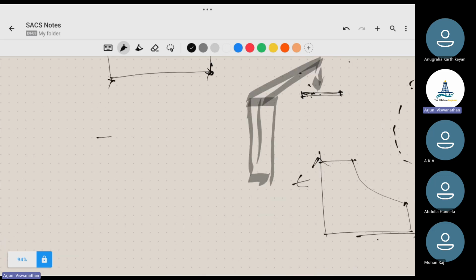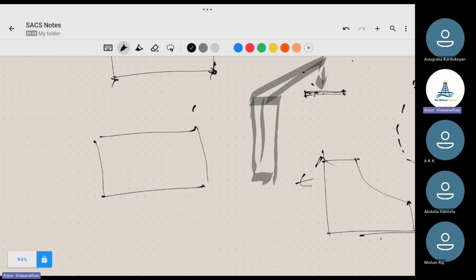Now, if I look at the plan view, there are two approaches to providing the weak springs. The weak springs we provide have 10 kilonewton per meter stiffness. In one approach, we give springs in X and Y axis at two corners. That will be enough.